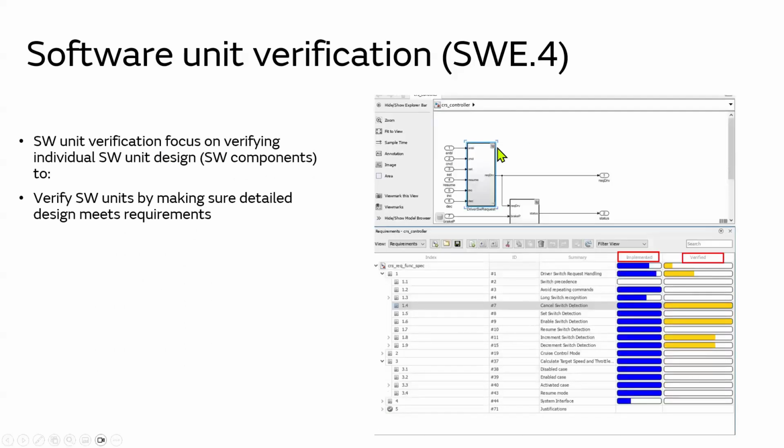You see, for the same software component, there are multiple of them with these requirements linked into that. The first tab here, which we did during the software unit design, checks if the requirements are linked, which is talking about the linkage of the requirement and that it is implemented. There is another one which is talking about requirements having been verified, so the verification of the requirement.